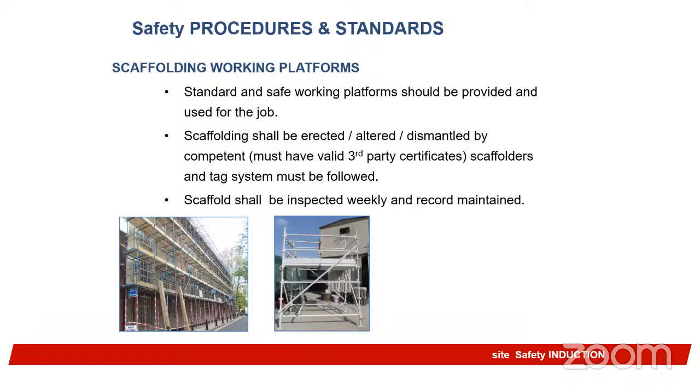There must be a proper access point. There must be a good working platform. It must be properly braced. There should be good installation and erection of the scaffold.